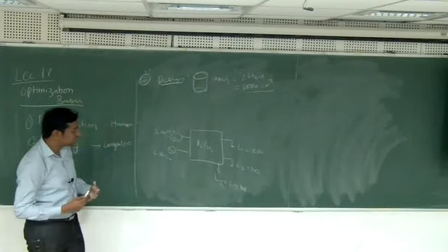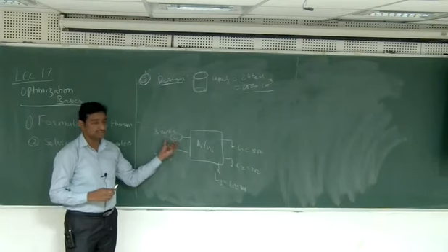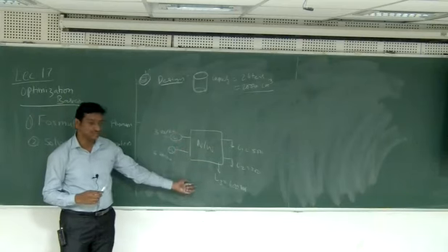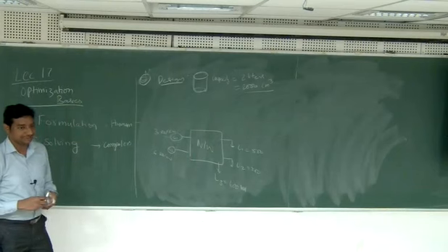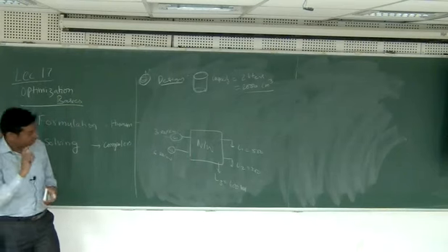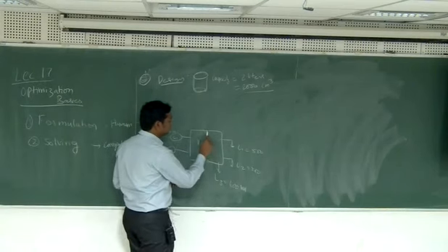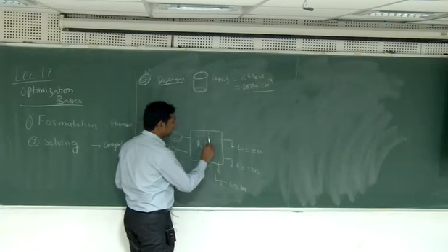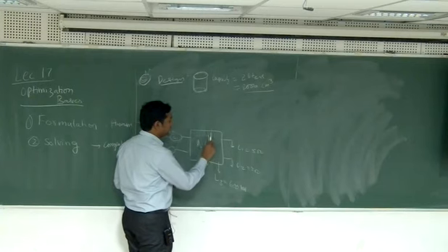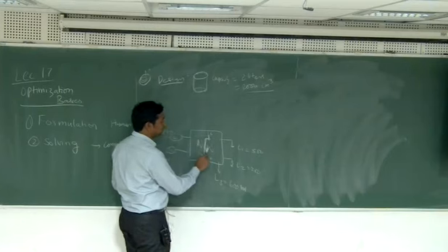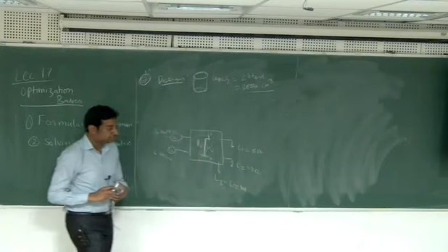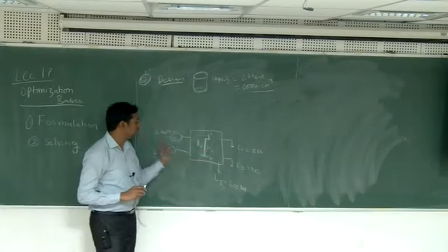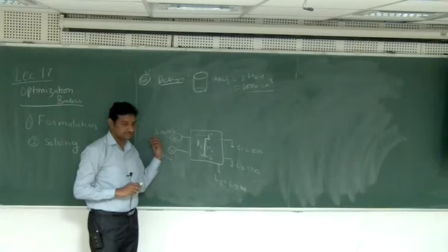So obviously your answer is to use generator G1 and generate the entire 1300 megawatts, so that your cost is less. But the problem is, in the network there is some line, let's say line number from 4 to 6. This particular line is getting overloaded. Because that line is getting overloaded, you cannot generate from it even though it is less cost.